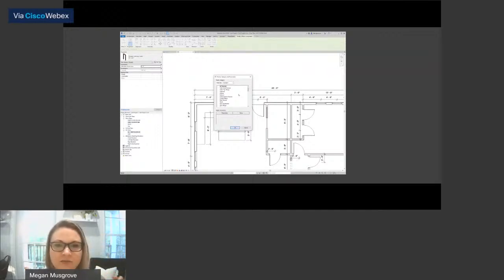And it has to do with how things relate to each other, and also sometimes how things will join. A lot of people will make anything they do in place just generic. I kind of have a system. It's one of those things, if you're using Revit, you're probably going to trip up with a family category somewhere. I think you're going to learn your lesson and never do it again.